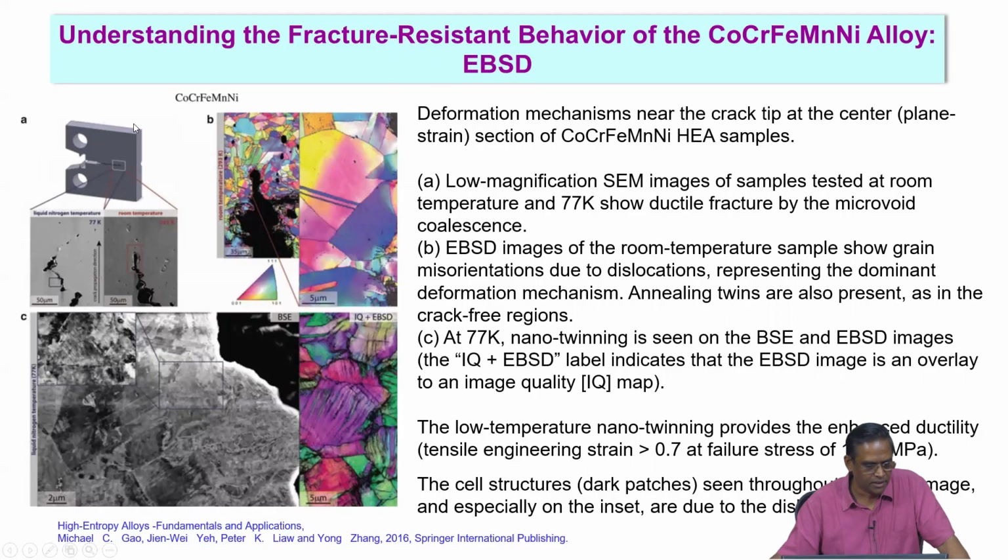This is the CT sample, compact tension sample, typically used for fracture toughness testing. And this is the pinhole. There is a pin inserted here, and then it is being pulled like this, and then you have a notch, and after the notch there is a crack, a pre-crack.